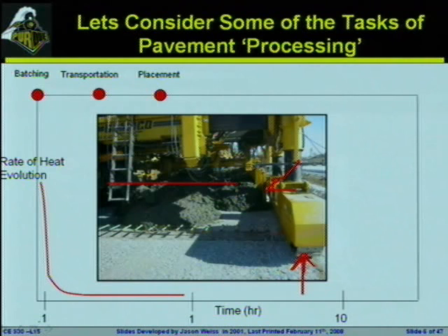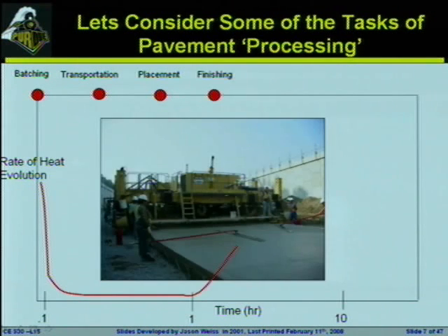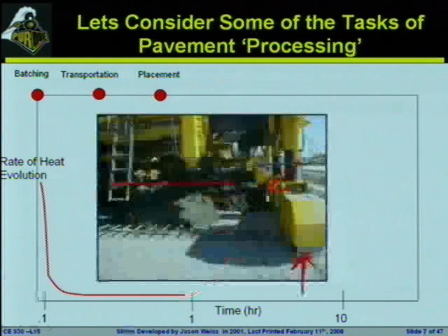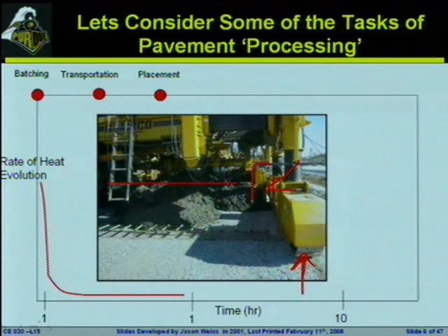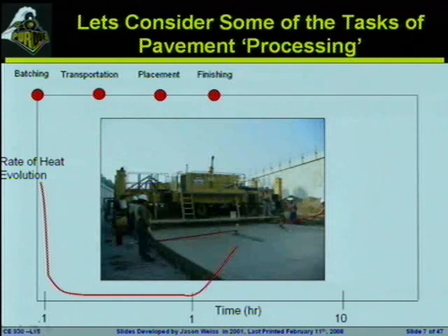Once that happens, we're going to start to vibrate the system, and it's going to be slip form paved out the other side of the system. So on the other side, we're going to see this is what the finished product looks like. You'll notice that there's no formwork because the idea was the energy is supplied in the paver, liquefies the system, gets things moving. During that point, the paver itself has some edges. So if you look really closely here, this is the formwork that's on the side. The basic idea is that once you've passed and the vibration has left the system, it's going to remain in this new shape. So here you can see that they're going to start the overall finishing process here, and